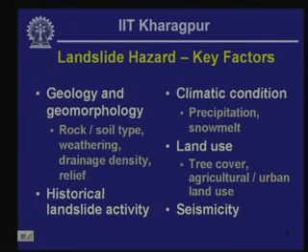For instance, in many areas in the Himalayas, landslide occurrence is greatly affected by whether or not there is a highway passing through that particular area, because in many instances, during the construction of the highway, hill slopes are steepened locally, and those hill slopes are often prone to landslide hazards.